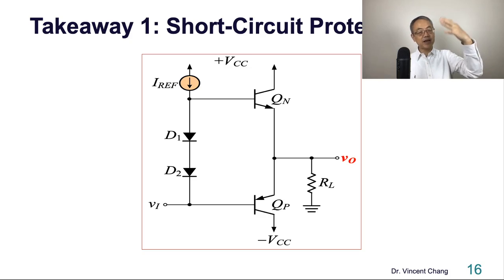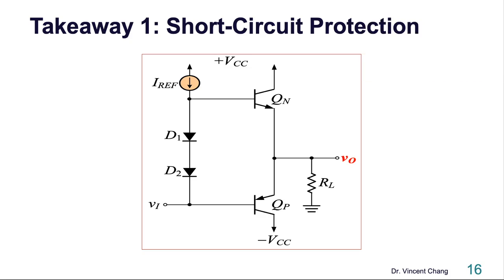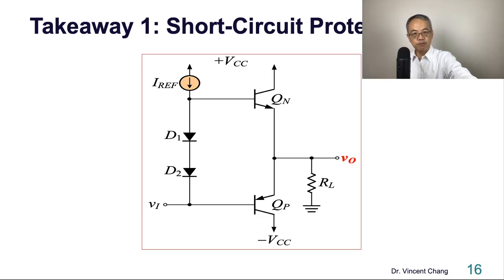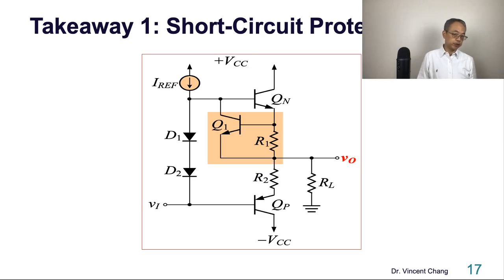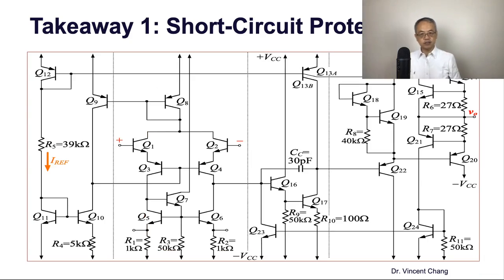What is the maximum current? So, takeaway. Number one, you know what the circuit is. You can identify the circuit. I encourage you, even if this is just a fill-in-the-blank, just draw this out. So I encourage you to memorize this short circuit protection. Okay? I won't ask you to memorize too many things, but this is very important. So memorize the short circuit protection circuitry. Okay? So where's the collector, the base? Where's the emitter? What's the relationship between R1 and the protecting transistor?